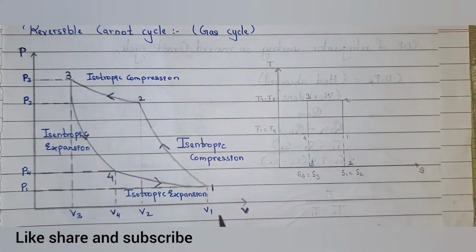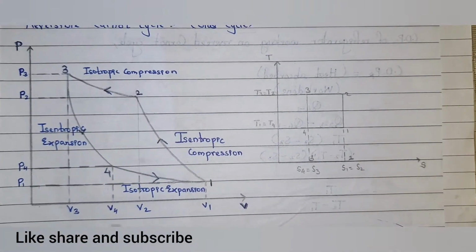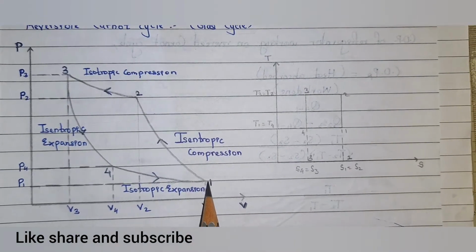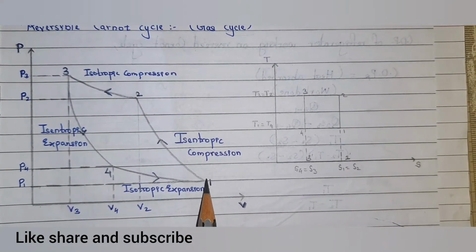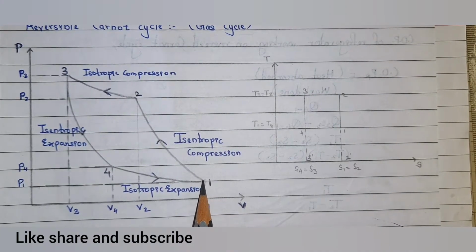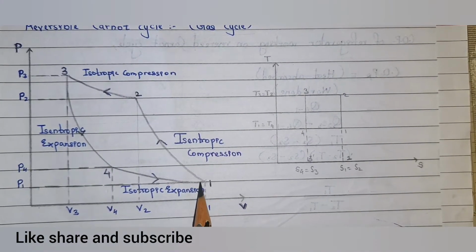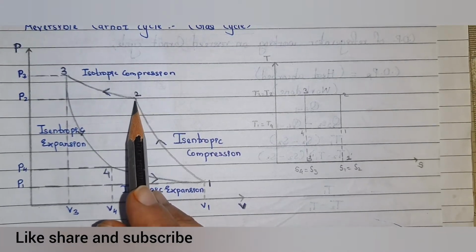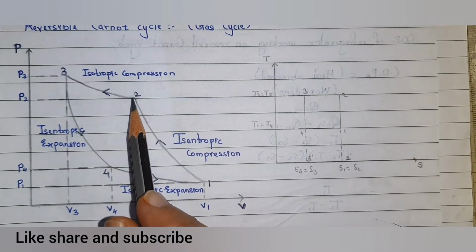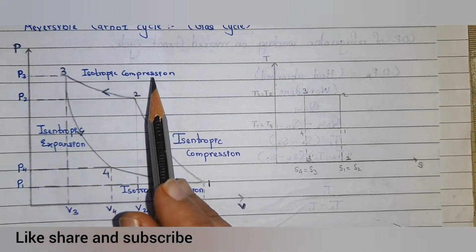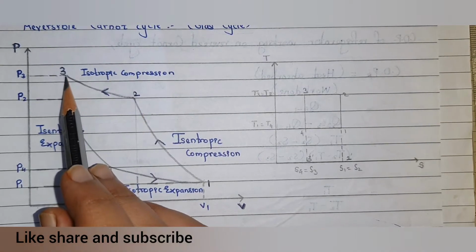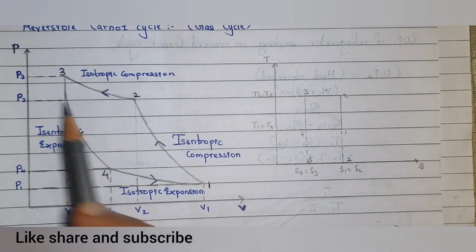So here it is P and here is V. Accordingly, the first isentropic process takes place, and we give this as point number 1. During the isentropic process, air is compressed isentropically, and the pressure increases and volume decreases. In isothermal compression, from 2, again the pressure increases and the volume decreases.